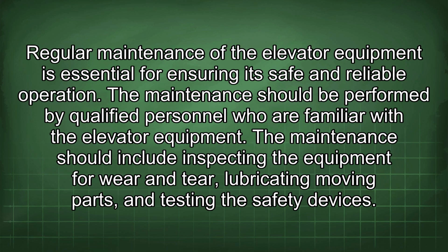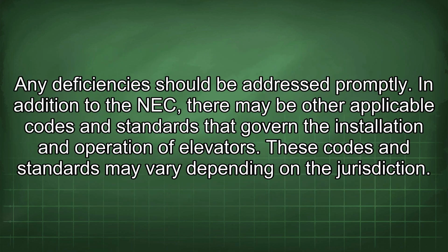Regular maintenance of the elevator equipment is essential for ensuring its safe and reliable operation. The maintenance should be performed by qualified personnel who are familiar with the elevator equipment. The maintenance should include inspecting the equipment for wear and tear, lubricating moving parts, and testing the safety devices. Any deficiencies should be addressed promptly.